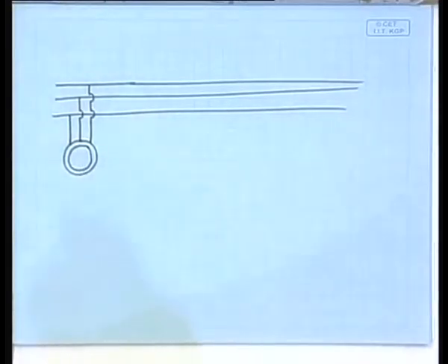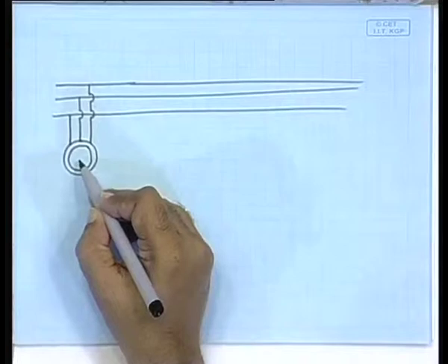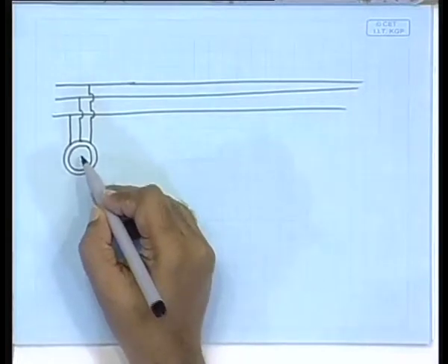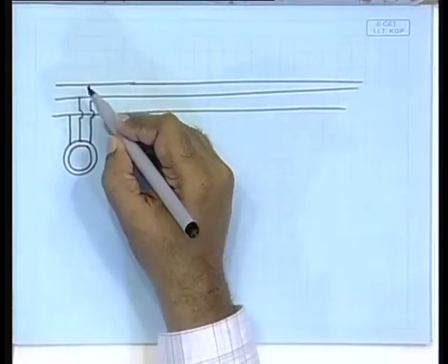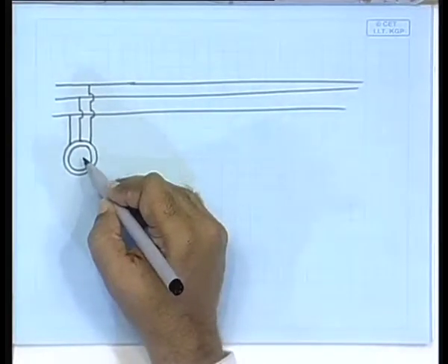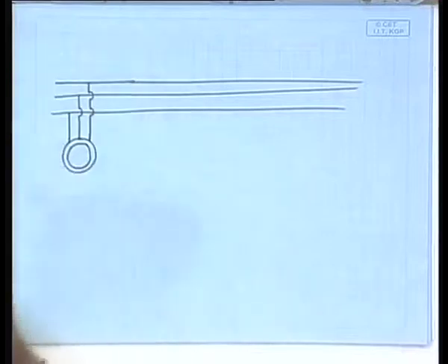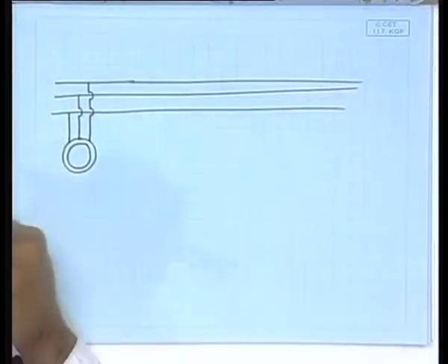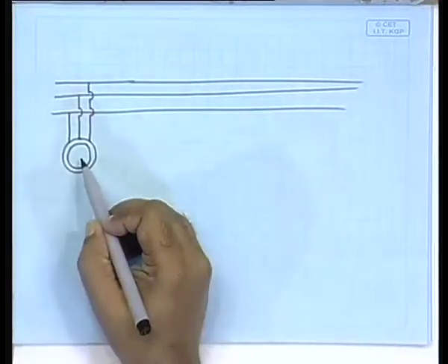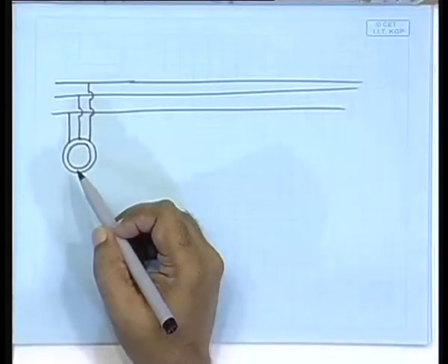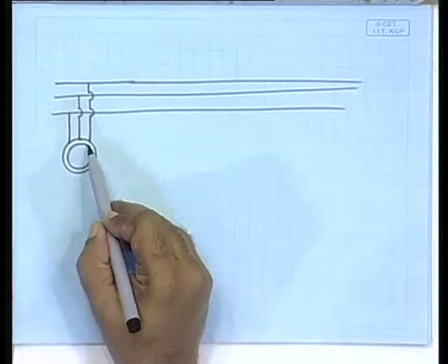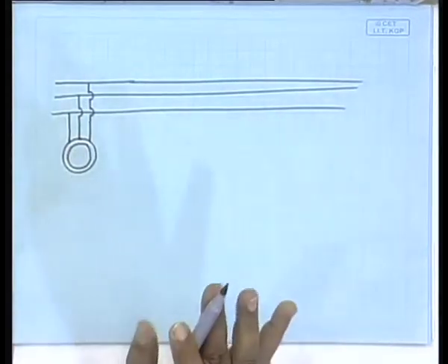So far you have learned that this rotor, as it is rotated, if the speed of rotation is bigger than the synchronous speed, then it will generate power, and that is what will be pushed into the grid. But then that can go on only till you have reached the rated speed. That means it is then pushing out a rated value of the power.